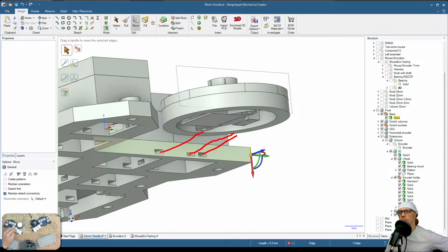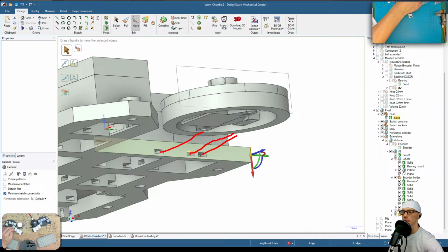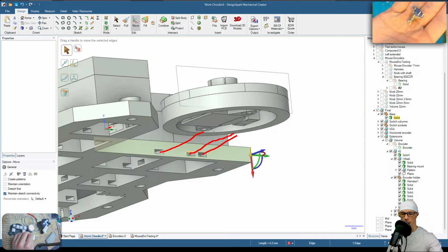We don't have any parts sticking out towards the bottom, like we would with this encoder. This encoder, as you can see, has its legs sticking down. So then we need some extra space, or maybe we can always trim those legs. But then it's a little bit more difficult to solder anything to it.